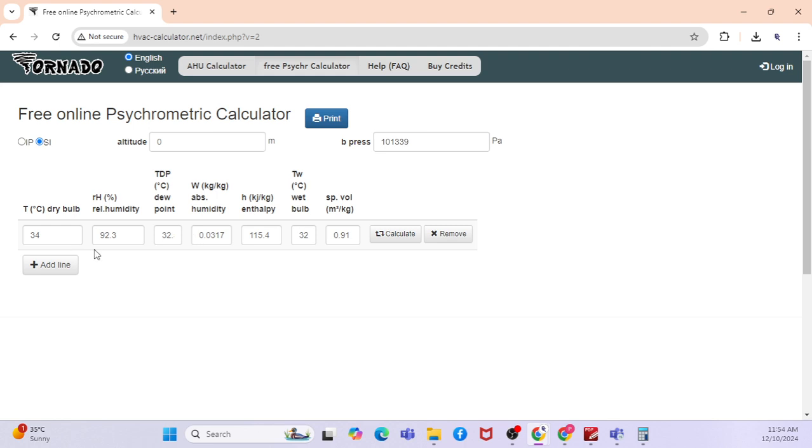Now I want to calculate the leaving temperature. So what leaving temperature is required is based on my supply temperature. The supply temperature for the standard air conditioning industry I will tell you is 11 degree, and the wet bulb temperature will be, say for example, 10.4. I will tell you how this value came, that I will explain later. So this is the calculation. You will get both conditions, right? On coil and off coil conditions.